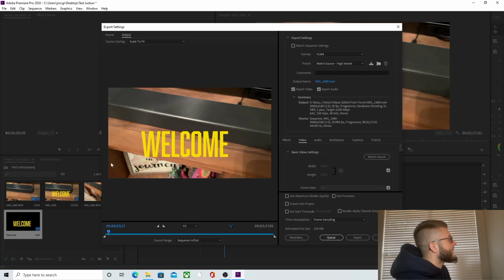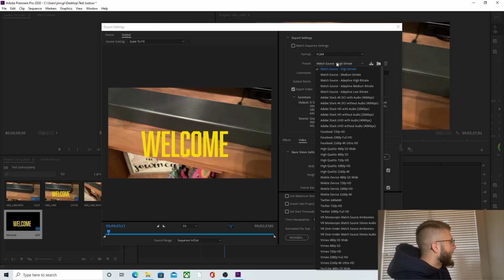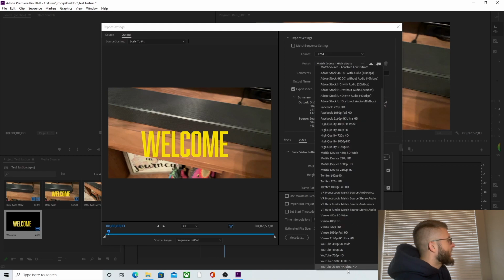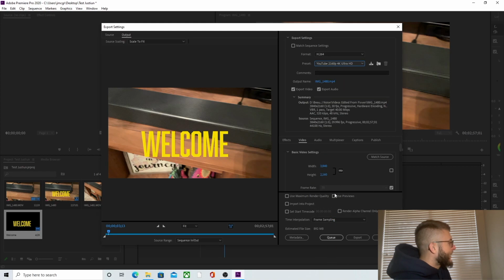So from here, guys, we can see that we have our footage on the left. This is just a sample and a preview, so we know what we're doing. I usually do H.264, and then I'll do 2160 4K video. The way you know that it's accurate is that at the bottom, your file size should be pretty big if you're doing 4K. This is almost a gig, and this is about 2 minutes of footage, 3 minutes of footage.